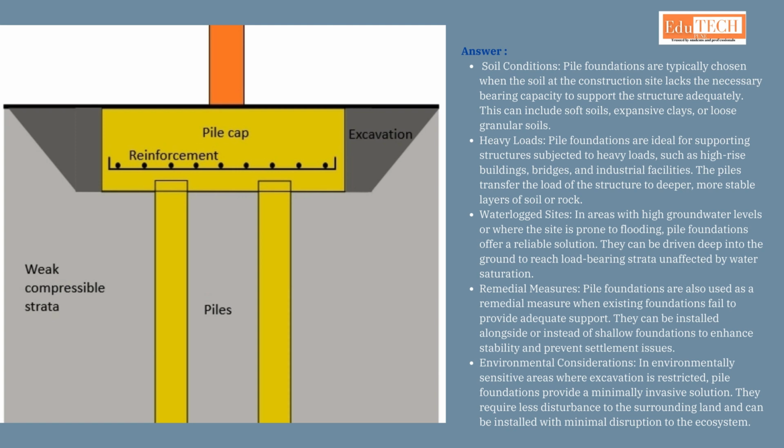Waterlogged sites. In areas with high groundwater levels or where the site is prone to flooding, pile foundations offer a reliable solution. They can be driven deep into the ground to reach load-bearing strata unaffected by water saturation. Remedial measures. Pile foundations are also used as a remedial measure when existing foundations fail to provide adequate support.